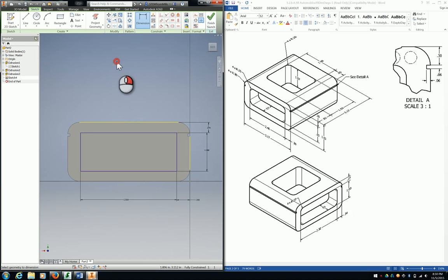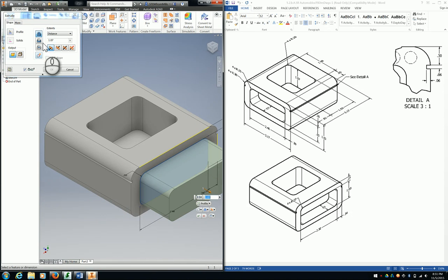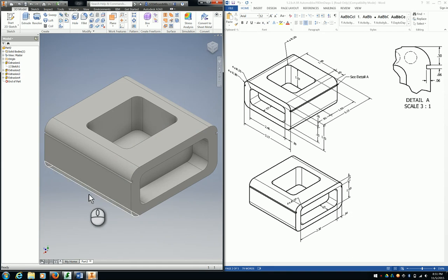So it's dimensioned, it's located. Finally, let's fillet it. It also has a radius of 0.2, so there we go. Oops. Yeah, I want to go in here. There we go. There we go. Alright, not as talkative now, it's more the same. Extrude it, go a different direction, cuts it out. What did we say? We said 0.57. Half an inch sounds about right.